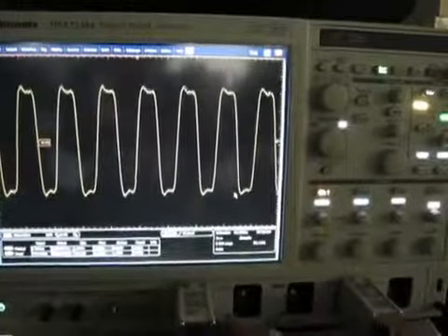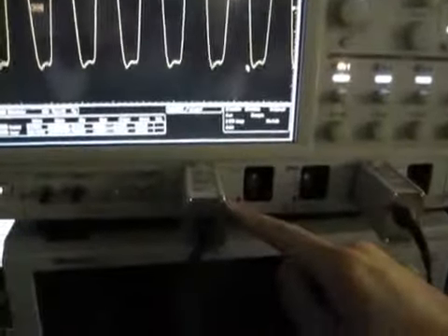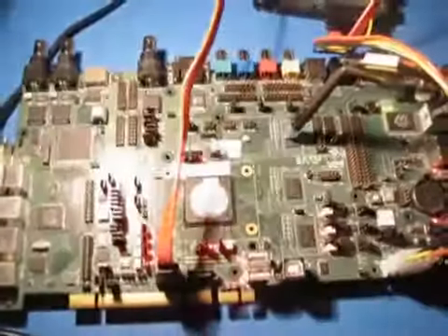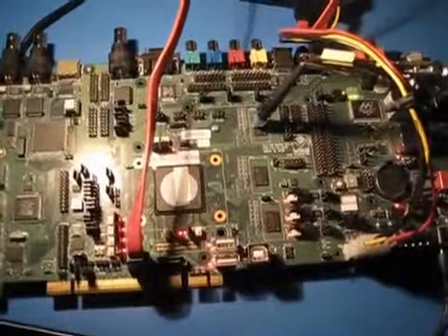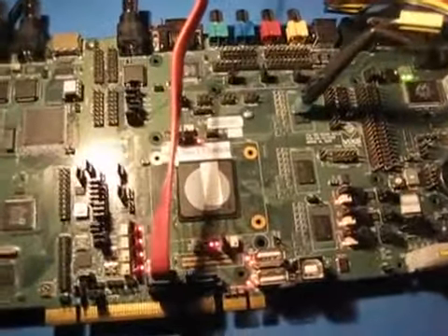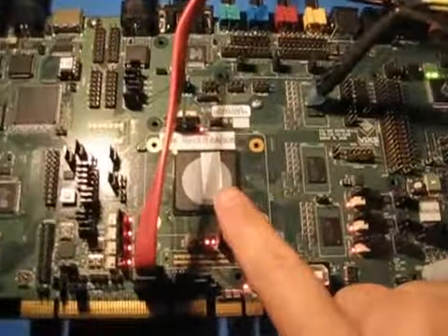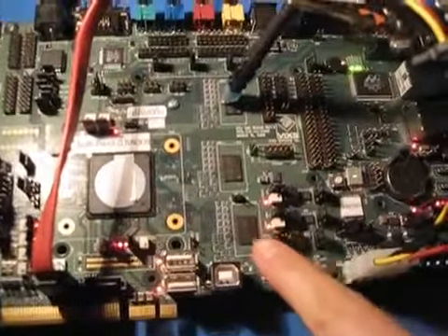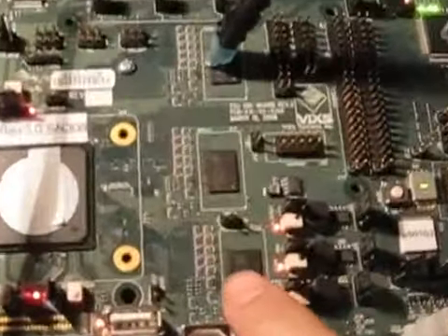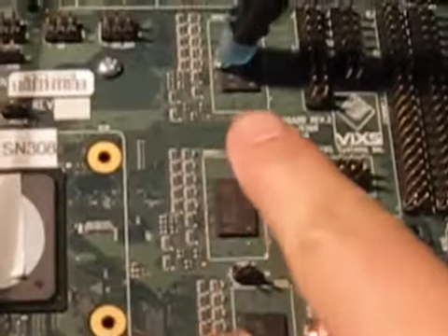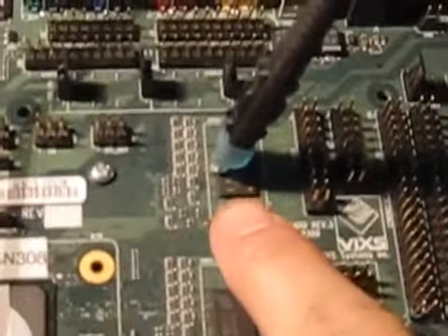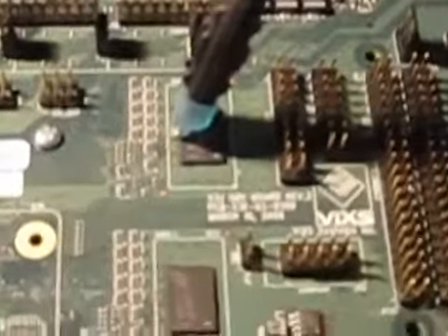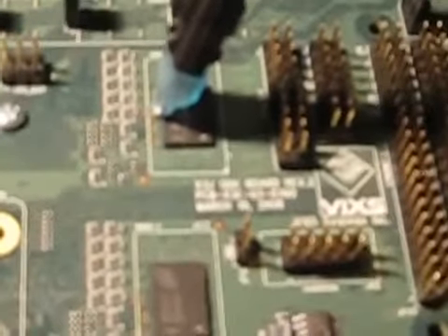The probe I'm using is a 5 GHz differential probe. So let's take a look at the device under test. Let's turn on the lamp so that we can take a close look at the current setup. On this board, we can see this is the CPU bus, and we have 3 DDR2 memory channels and 3 memory modules on the board. So first one, second one, the third one. The probe I'm checking is connected to the clock signal on the third memory channel.